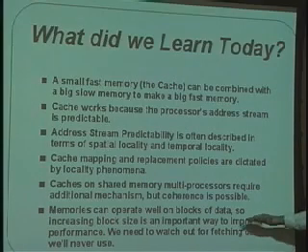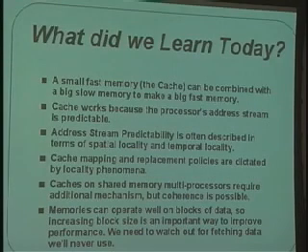And then finally, there's this thing having to do with block size. Block size is a very important way to improve the performance of the system, in particular because the throughput of these large RAMs is so much higher than 1 over their latencies.